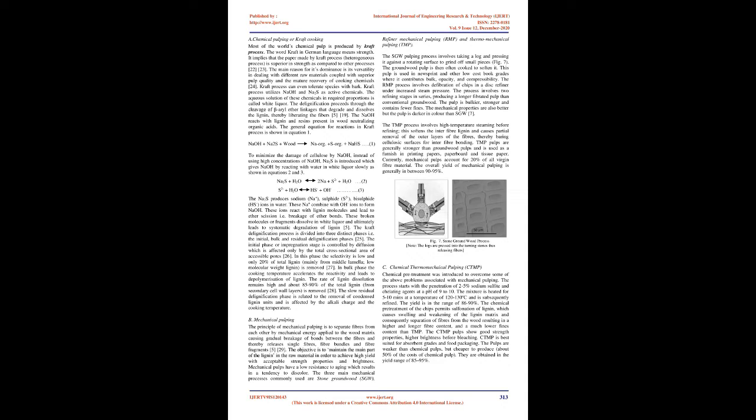During the pulping process, the chemical structure of cellulose also changes. The degree of polymerization value, weight average, of cellulose decreases from 3500 to 600-1500 when wood is transformed into pulp. 5. The pulp is manufactured from wood or non-wood materials using chemical, mechanical and chemical thermomechanical pulping (CTMP) methods. A. Chemical pulping or Kraft cooking.